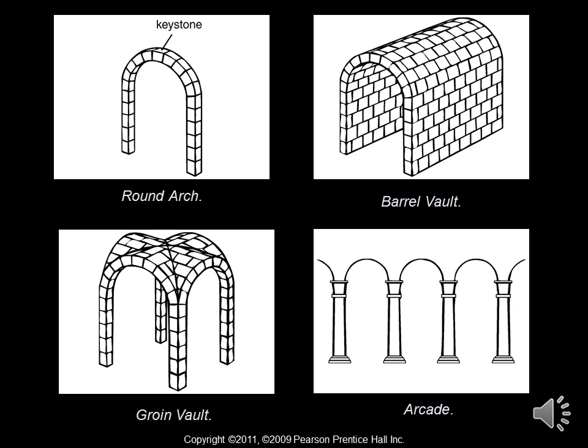When constructing an arch, there's a support system that holds the stones that are basically forming the vertical supports in place until the wedge pieces come to the final point where there's only space for one left. That's where the keystone goes in. That basically keeps everything together, allows the wooden supports to be taken away. That's for the round arch.